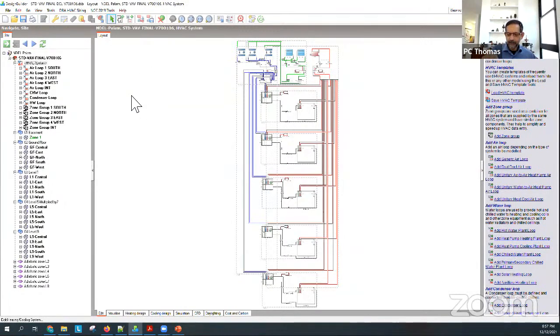So obviously we have a chilled water loop, we have a hot water loop, we have air loops, then we have zone loops. Okay, so 5 different loops. And you can recognize all of them here. Here's your chilled water loop. Here's your condenser loop. So that's your cooling tower, making your chillers efficient.